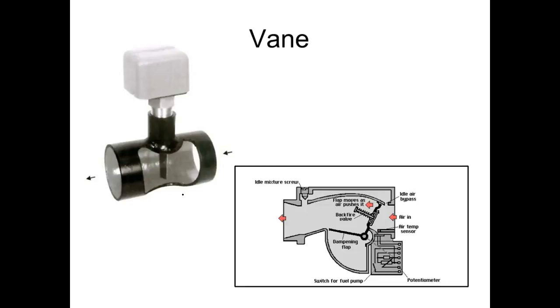When the flow comes in, what does it do? It moves the vane. Then here they've got it connected to a potentiometer. So when the vane moves, it changes the potentiometer, which gives us an electrical output that indicates the flow. Of course, we'd have to know the transfer function, right? So we'd have to know what voltage we get out relative to flow. And that would probably be in the specifications. Everybody okay on this? Pretty straightforward. A vane, and this is really, really popular.